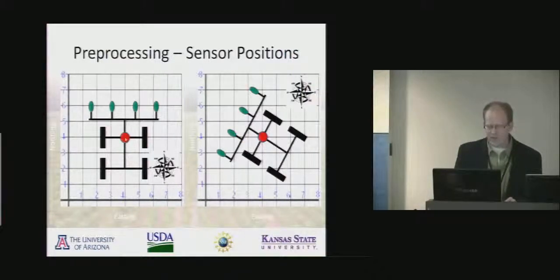The northing offset would be from here to here, that distance. It's a positive distance from 4 to, say, 6. So for this particular example, you would put in a northing offset of 2, we'll call it meters. There's no unit here, but we'll call it 2 meters.